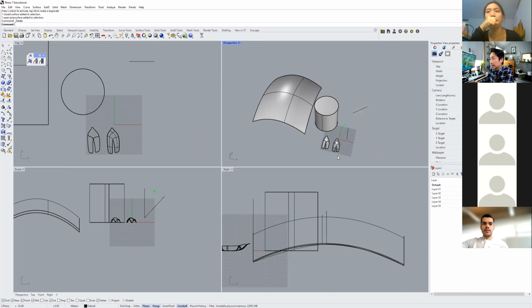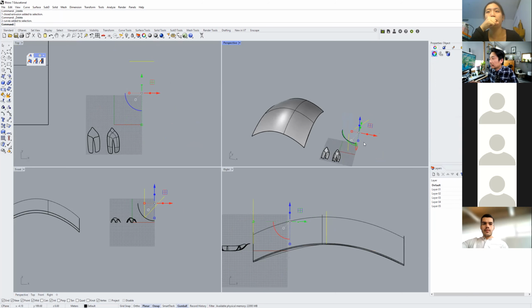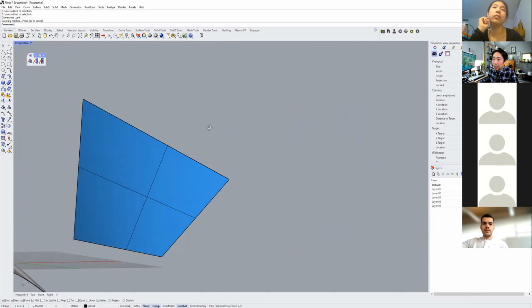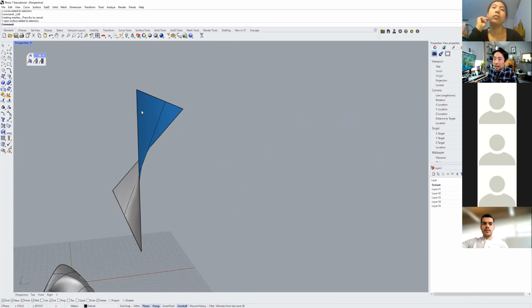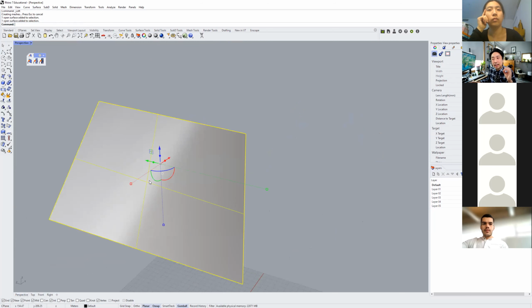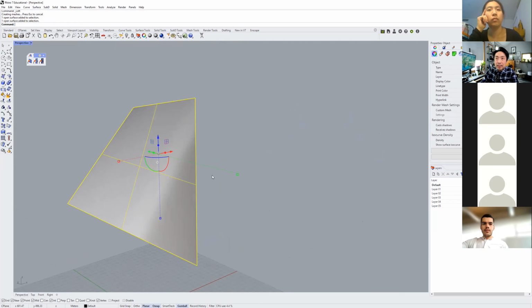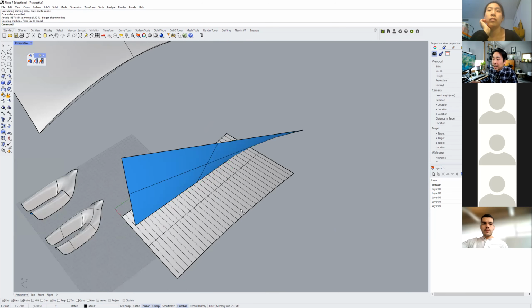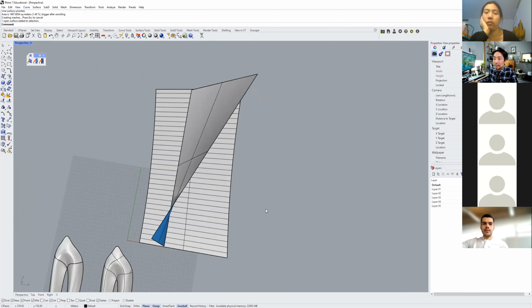Yeah, my workspace is getting a bit too messy in here. Okay, so I have a surface that's been lofted. So the surface is curved, but as I cut sections through it, I always get a straight line. That means that even though this surface has curvature, it's actually a singly curved surface, right? Surfaces like this can easily be unrolled, right?